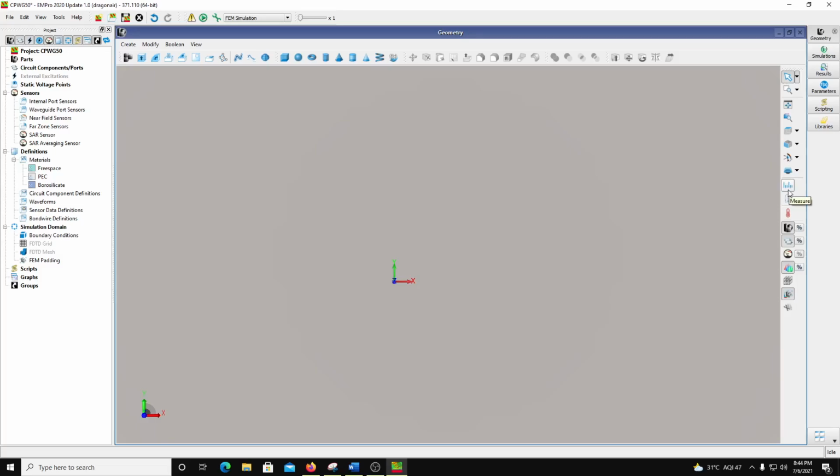Now this one here, it says measurement. So just like your right click measure in Momentum, you can measure between two edges or between two vertices. In 3D you can measure using this tool, right? And then this is the solid connectivity tool, which you have already seen in Momentum. So that's that. Okay, field radar. So basically you can pick a test point in the field and look at its values.